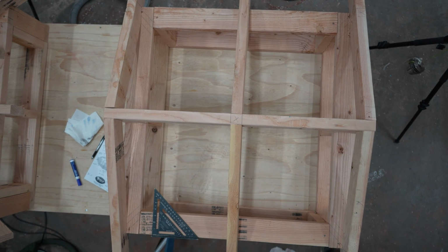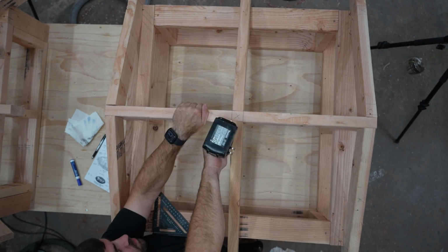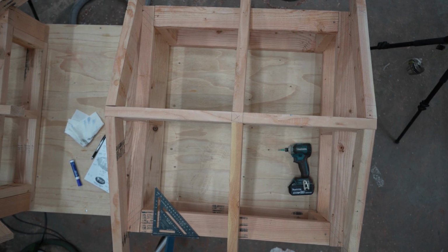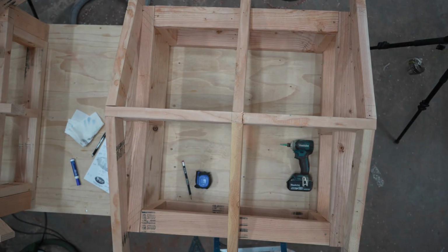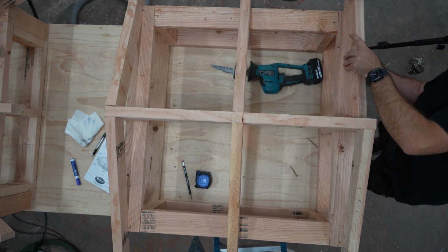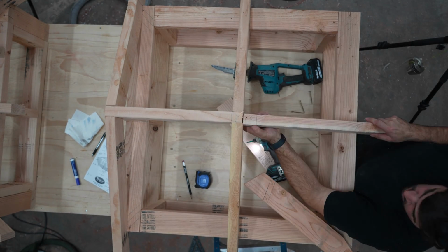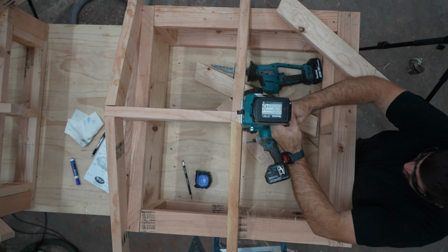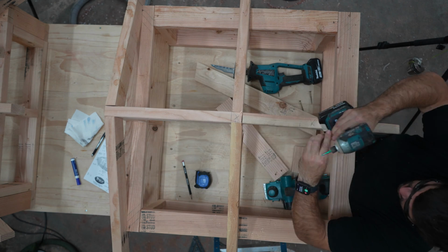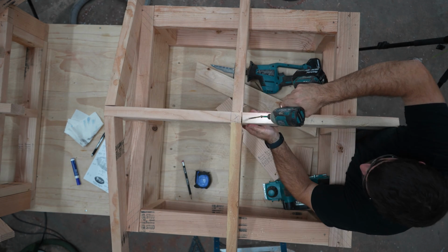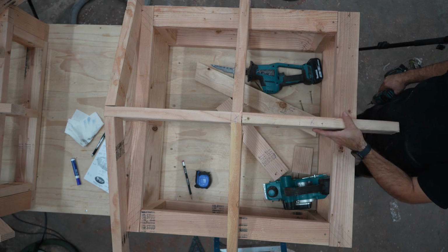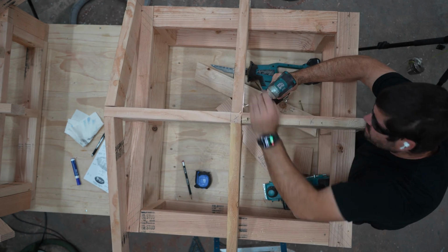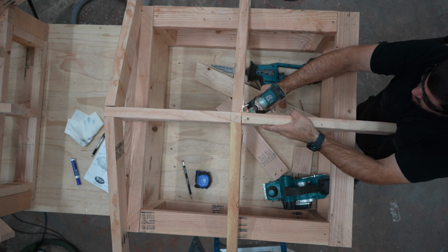On to the framing section. I'm going to use the model we used in our last video, so I need to cut off 17.25 inches from the ridge board. I don't want to cut off the ridge at 18 because then the points of the intersecting boards would be slightly higher than the ridge board. And in order for my plywood sheets to sit nicely at the peak, I would need to plane a bunch of edges down. Once it's cut down, I add back one of the common rafters I removed, attaching it this time at the center of the run, and then it lines up with the top of the ridge board. Now I have a corner for my hip to nestle into.